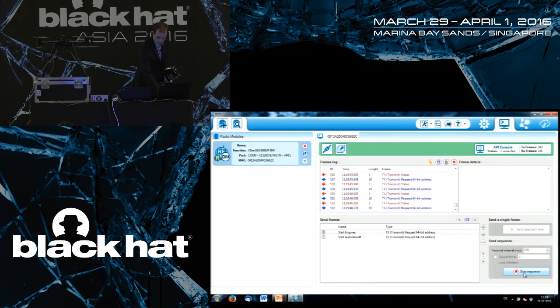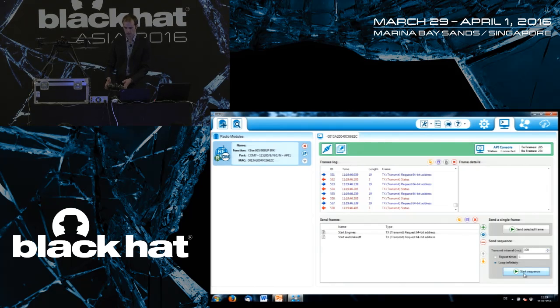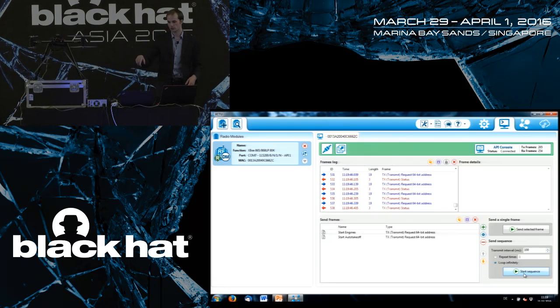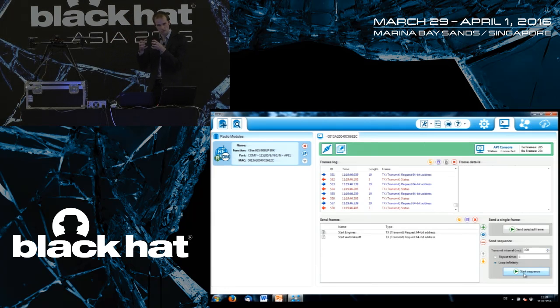Okay. I will stop that and shut it down manually. So what you did see now, it stopped shortly, is because I'm using a static power source here instead of a battery. And with a static power source, this power source isn't able to provide enough energy if all 8 engines are starting at the same time, which is why if too many amps are drawn from the power line, then the voltage breaks down, which is why it shortly stopped and started up again, because it's still receiving the command start engines, and then it's starting up again.